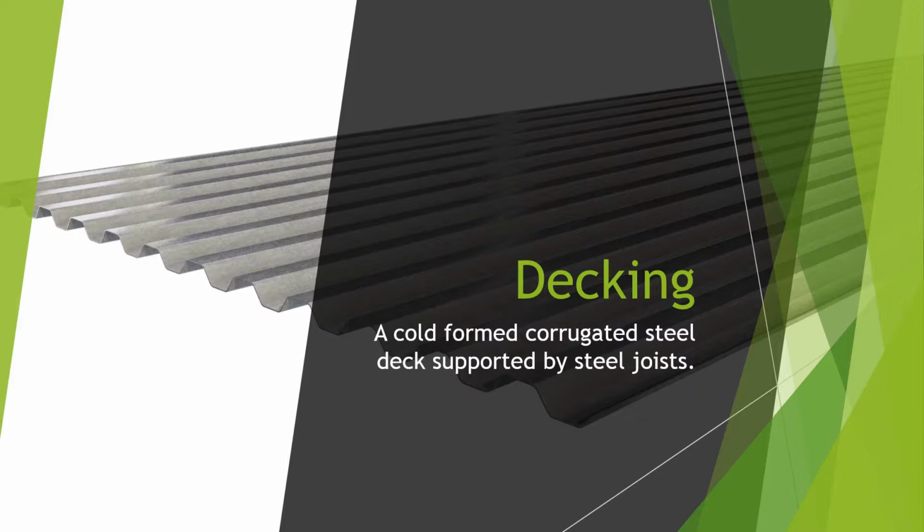Sometimes that decking, when you're laying it down and you're starting to lift it up, acts as a sail if the wind gets underneath, and it can take someone right off a building. So you got to remember, special care and attention is required when erecting decking, or laying. We call it laying down decking. A journeyman will help with having lots of prior experience and knowledge when you're doing this, because like I said, a lot of care and safety got to be taken.